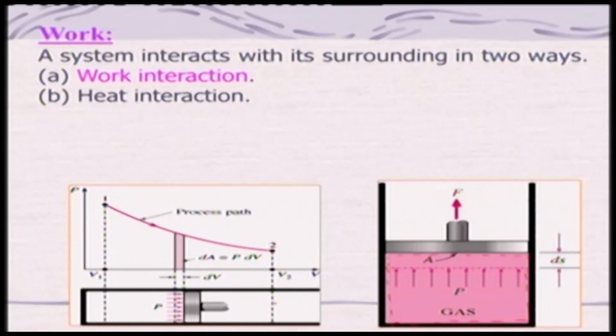All the time you can think of it as attaining quasi-equilibrium, because you are changing the force by a very, very small amount, such that it attains mechanical equilibrium. One can also consider it a reversible process, because it is very slow and there is no friction between the cylinder and piston, or anything else which would make the process irreversible.